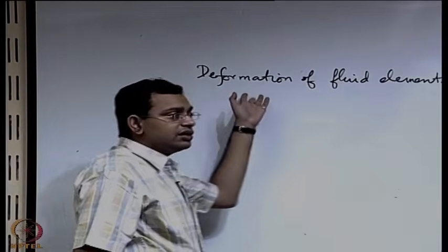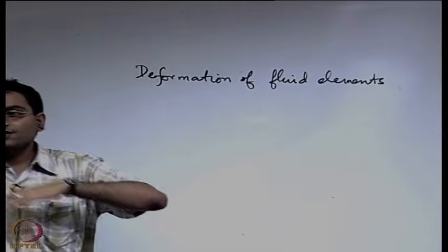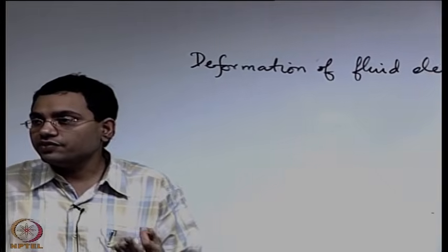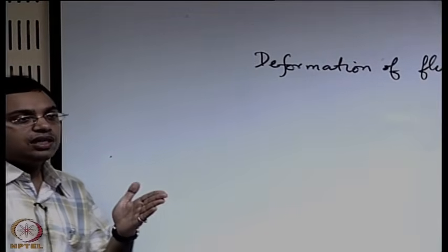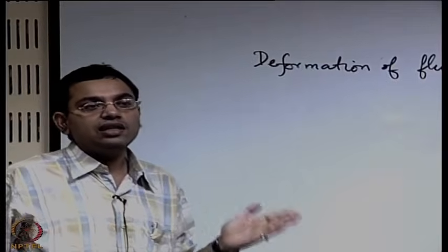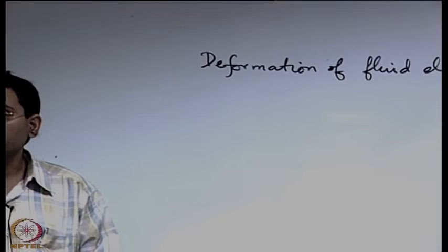Why is this very important? Because we have seen that fluids are characterized by deformation: they undergo continuous deformation under the action of even a very small shear force. The relationship between the shear stress and the rate of deformation is unique to the constitutive behavior of different fluids. So we must first understand how to characterize deformation of fluid elements in terms of the velocity components.